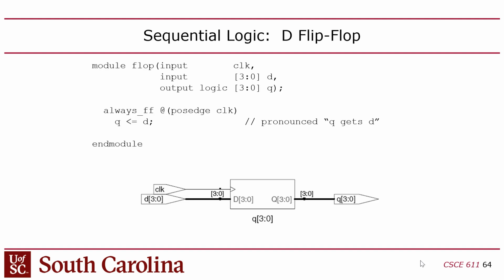I was going to do a demo of this today. I just ran out of time though, but if you use always_ff, you can make sequential logic that's clocked. The idea is that you have to specify a sensitivity list, which is something you don't need for always_comb.